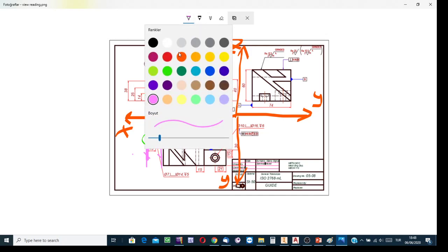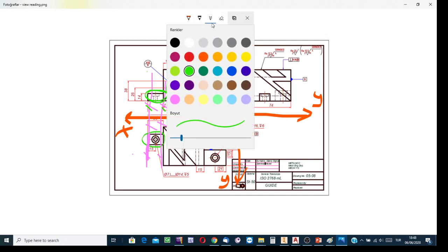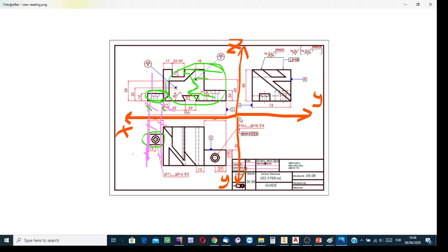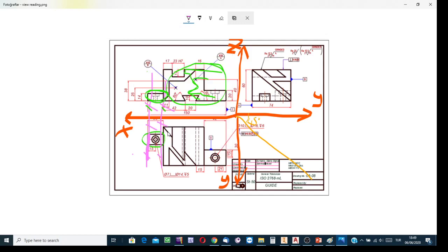We have, let me take the same color, a mitral line, and this inclined line, its inclination angle is 45 degrees, is used to transfer the delta y values from top to left or vice versa. Here, after saying that this is the front, this is the top side, then follow the transfer lines.